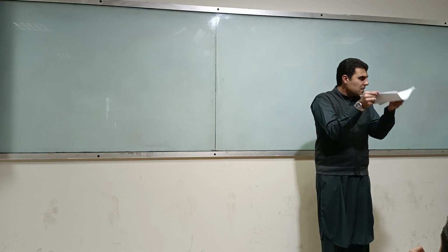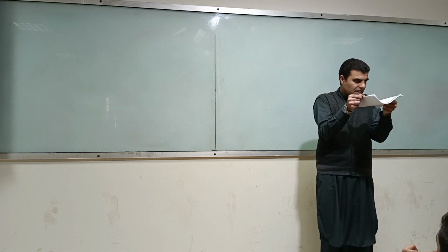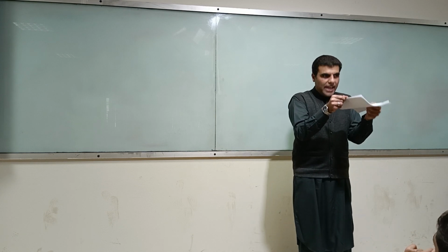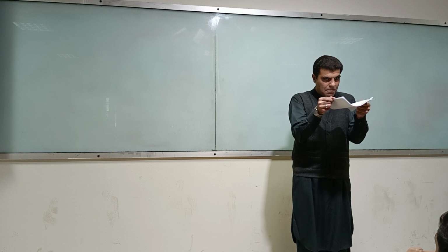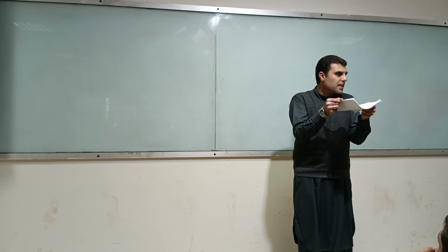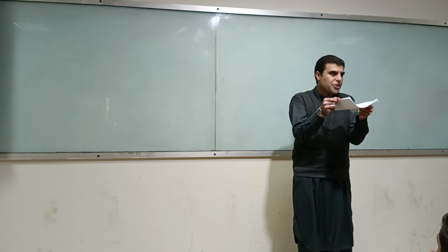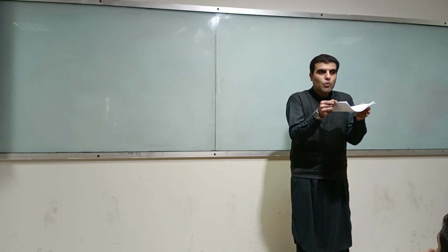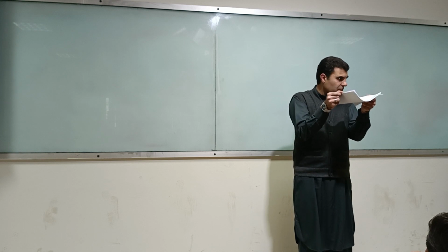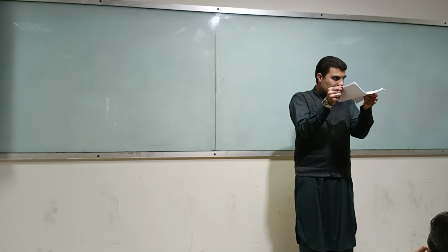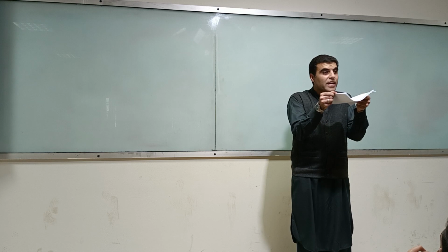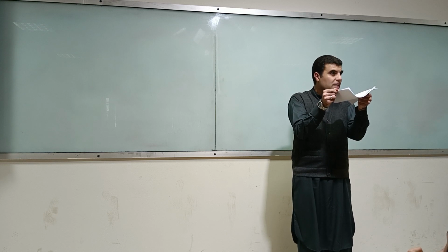Okay, so imagine my left hand is point A and my right hand is point B. So at point A we have to work out the compatibility equation, or the equation of the elastic curve. So what is the equation of elastic curve at point A? The deflection is 0 and the rotation is 0. Isn't it? Yes. There is no rotation. However, at point B rotation is unknown, only the deflection is 0.